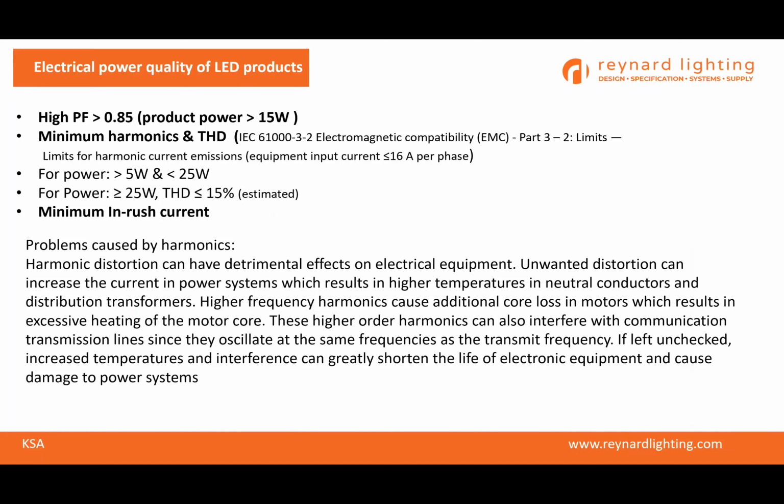All the LED products have to be with high power factor, and the definition of high power factor is more than 0.85. And the high power factor is required for products higher than 15 watts.